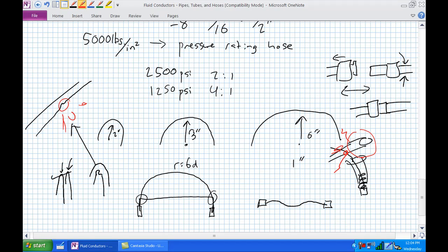If you ever see a hose that has developed a pinhole leak and is spraying high pressure hydraulic fluid, by all means, do not attempt to grab that with your hand. You need to go ahead and deactivate the system and fix that hose, because if you grab onto that thing, that is incredibly high pressure hydraulic fluid. Not only is it going to cut you, it is chemically caustic to your body. So maintenance of pipes, tubes, and hoses is essential to the performance and safety of hydraulic systems.